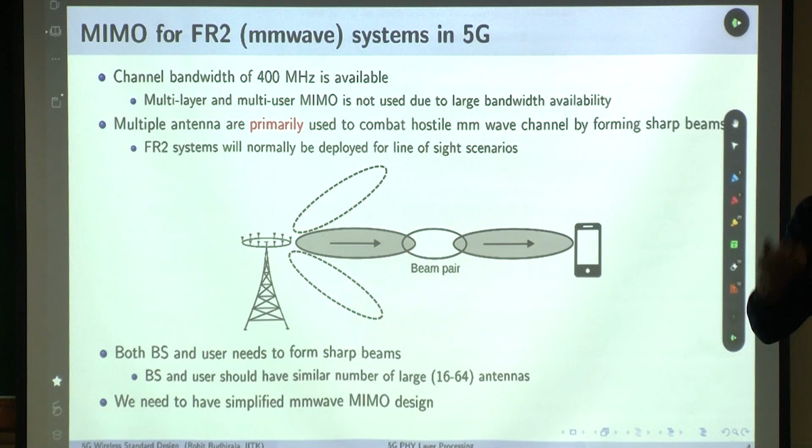Even if you want to put, let us say, 10 RF chains here, you cannot, because there is no space on the UE side. Each RF chain, remember, has 2 ADCs, one RF up converter, one low noise amplifier, and each of them is going to occupy space and guzzle a lot of power. Your mobile will run out of battery in no time.